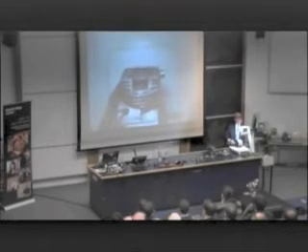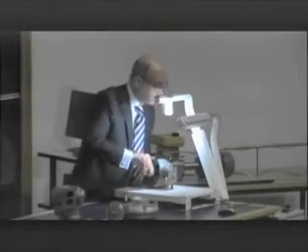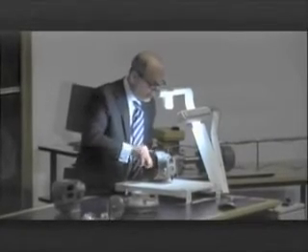When it gets to the top, somewhere here, then I've got my spark plug, which ignites the charge, and now power is produced, so this moves down. And now the exhaust valve opens, which is the bit I'm interested in, I'm afraid. Exhaust gases, which have some remaining temperature, not to say a high temperature, and pressure, are expelled through that valve into ambient. So inlet, compression, bang, exit. Right, so you've never seen an engine, you've seen one today.